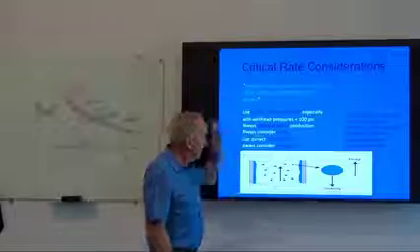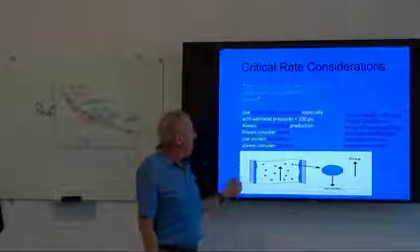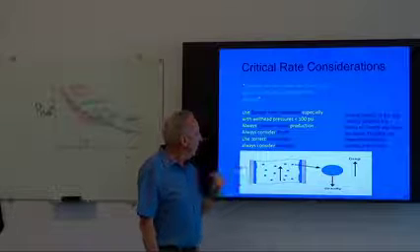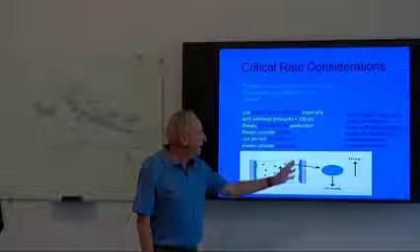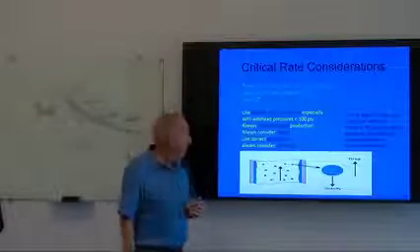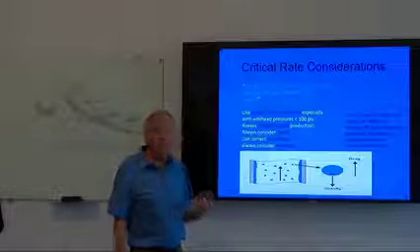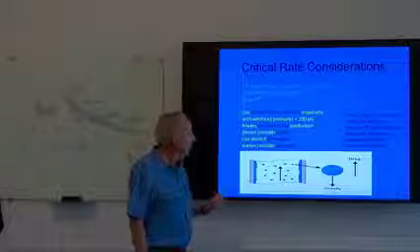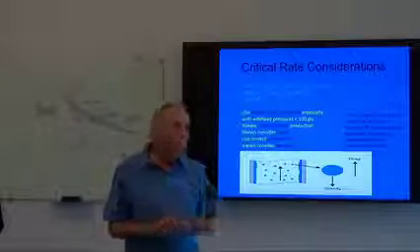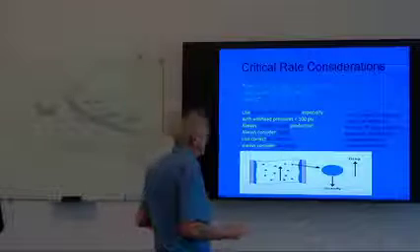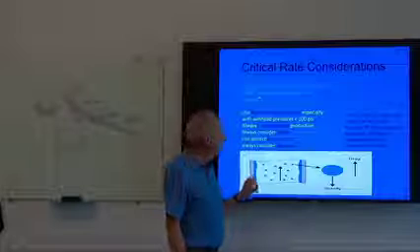So here's a cross-section of a piece of tubing or a pipe, and we have gas flowing up through this pipe. We have liquid, some of which is deposited on the side of the tubing. It's a fully mixed or highly mixed and wetted setting, and we have droplets of liquid, let's say in mist form. We can describe it different ways, going up through the center of the well.